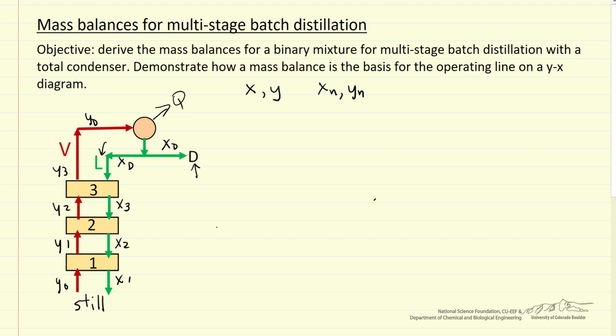The other term that we're going to use is the reflux ratio. So that's going to be the molar flow rate L, liquid, over the molar flow rate D, the distillate that we collect. So V, of course, is L plus D, right? V is the flow rate coming into here, and we split it into two streams.